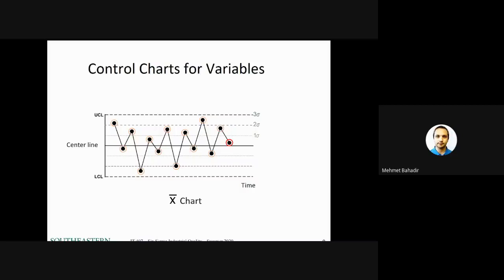Let's say in the morning you're going to the plant floor and you are collecting 10 screws, all right? And then you measure their ODs, outer diameters, 10 screws in the morning, all right? And what you're going to do is collect that data, read that data, and record them. The next thing you're going to do with the data is calculate their average. The average is going to be represented by X bar, right?